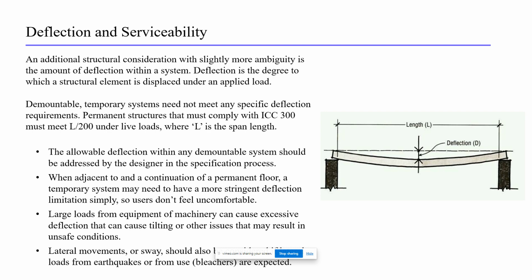We talked about various types of lifts being used on the demountable systems. Where that's used, you don't want to find inconsistent behavior between the solid floor adjacent to the demountable system, where you might drive a man lift over it, and find that it's very soft where you have the demountable equipment. Contact a qualified professional when you're talking about creating a specification for deflection. Too strict a limitation could unnecessarily double or triple material costs.